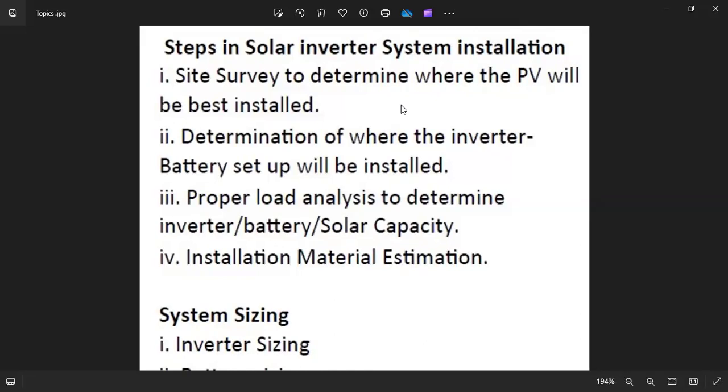If you have come across any lithium-ion battery that is bypassed, because they are cells that have 3.3 point something volts, if you decide to connect them in series, you get your desired voltage and power your inverter. If you power it without a BMS, definitely know that you are actually sitting on a time bomb.